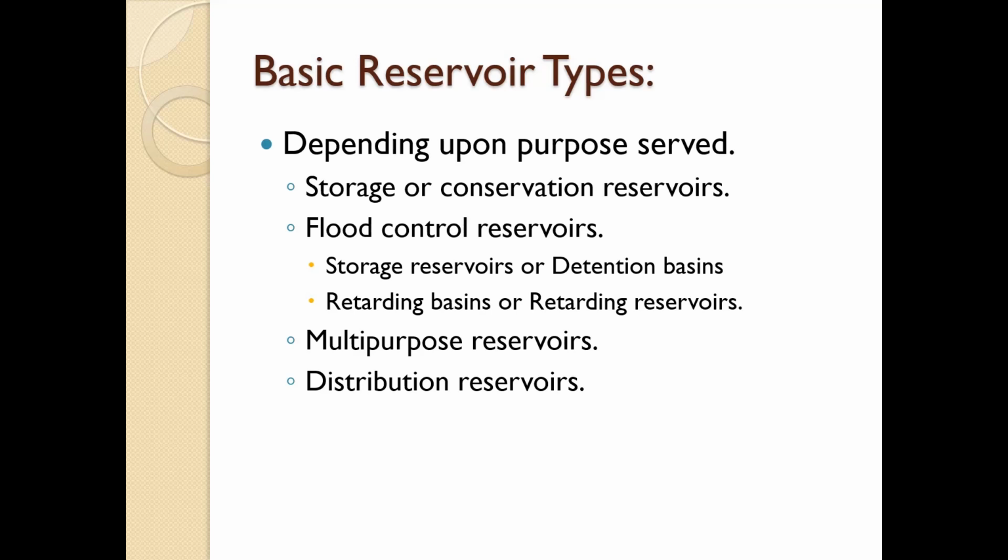First is the storage or conservation reservoir. A city water supply, irrigation supply, or hydroelectric project drawing water directly from a river or a stream may fail to satisfy the consumer demand during extremely low flows, while during high flows it may become difficult to carry out the operation due to devastating floods. A storage or conservation reservoir can retain such excess supplies during periods of peak flows and can release them gradually during the low flows, as and when the need arises.